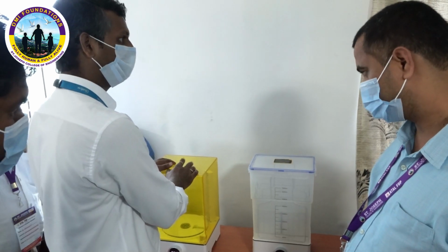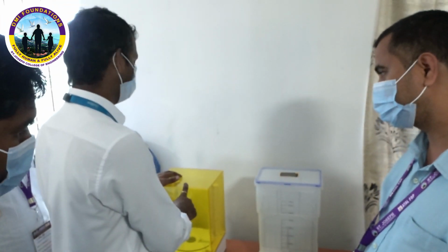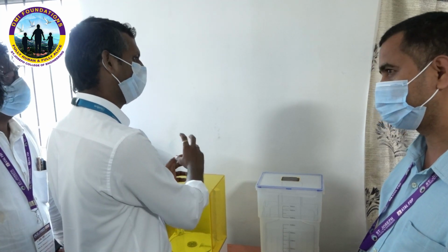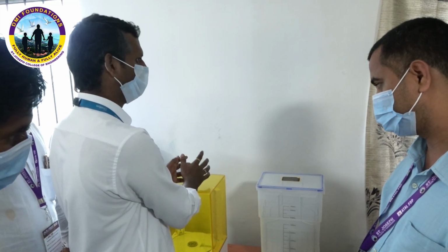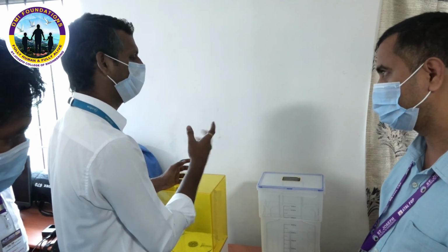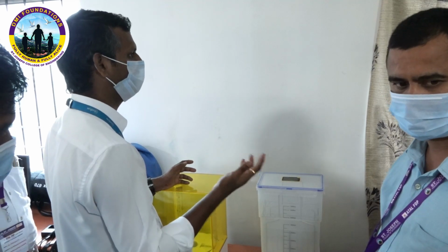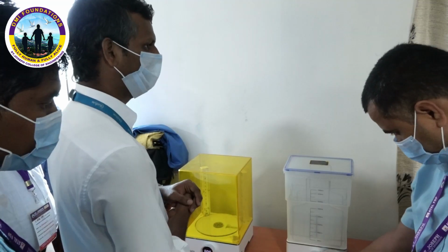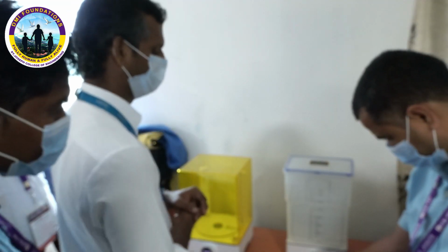So that is also possible, but they use a different formulation of resin. For those resins only we have to keep the heating. Not for all; for standard resins it will work. For tough resin, rigid resin, those only we have to switch on the heating also. Sir, will it be applicable for thermoset resin? Plus we are not using any UV light.